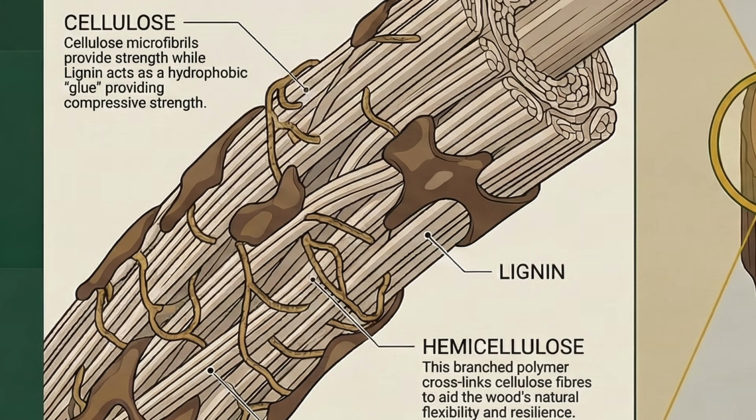So, Rich, tell us more about fungi, what they actually do, what they are, etc. So essentially what fungi is doing is it's using the cellulose and the lignin that we've heard about in the previous episode to break it down as a food source. And it actually has enzymes within the fungi that break down those structural components, which is why we end up seeing the decay as it is. You see it shrink, you see the cuboid, you see the cracks that form with it. And it's because of these enzymes that are breaking it down, because it's using it as a food source to grow the fungus so it can then thrive.